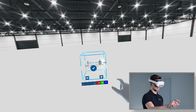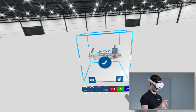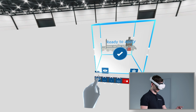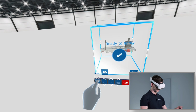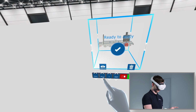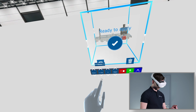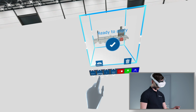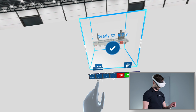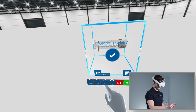One of the most powerful tools inside Hololight Space is the loading cube. The loading cube is an easy way for the user to assess and visualize the file and its properties before confirming the loading in the space. This tool is very important because it allows, for example, changing the measurement system, changing the scaling factor, and working on the orientation of the file, and fixing all the options that usually during the export process could end up creating a different visualization of the same CAD file.